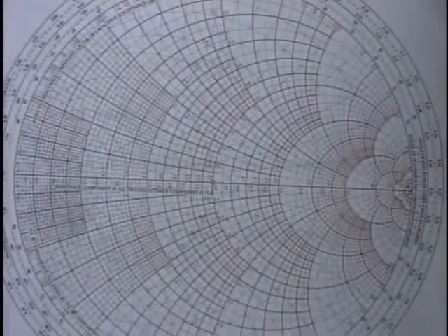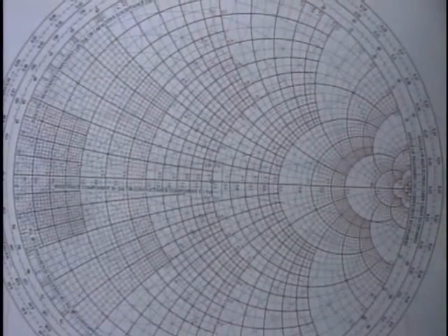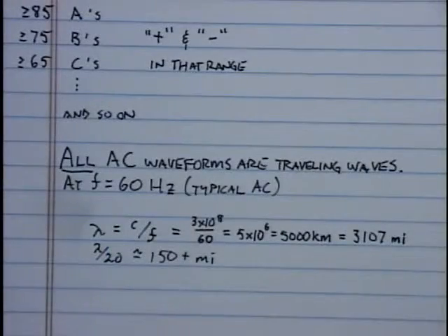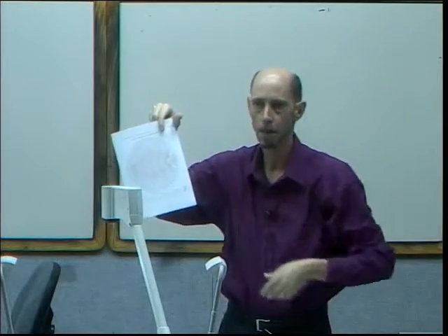There's another type of Smith chart that we're going to be making use of called the YZ Smith chart. It's this colorful thing. You can't see it as well on the overhead, but it's red and blue, rather than just black and white. It's two Smith charts, one of them rotated by 180 degrees and then plopped down on top of the other. You're going to need both kinds of Smith charts. This so-called YZ Smith chart, the more complex one, is on the Blackboard website as well, under the title YZ Smith chart. Download it and print it out.